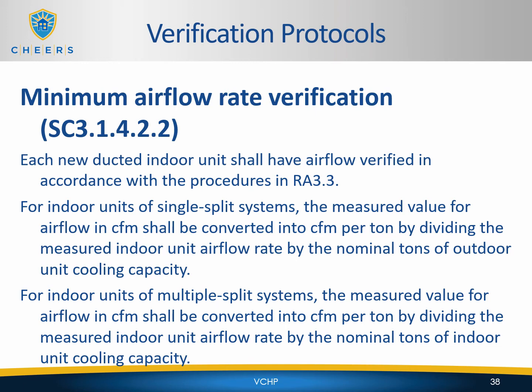So these are a little bit different. If it's just a single split, you're going to use the outdoor unit or the condenser cooling capacity. For multi-split systems, you're going to use the cooling capacity of the indoor unit, as the condenser is going to be a much larger capacity than that one indoor unit, and so it's not expected to have as much airflow as the outdoor unit.